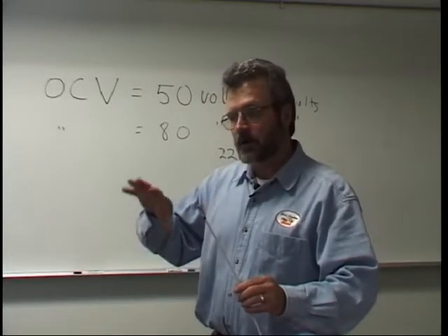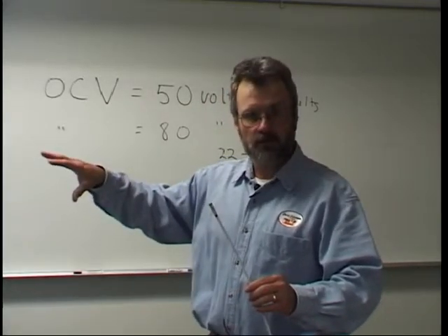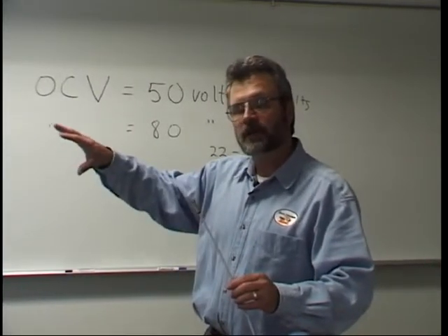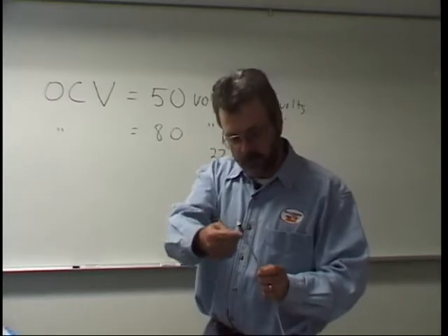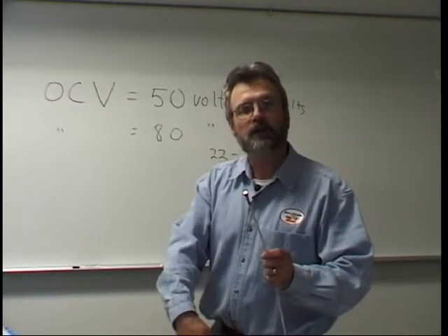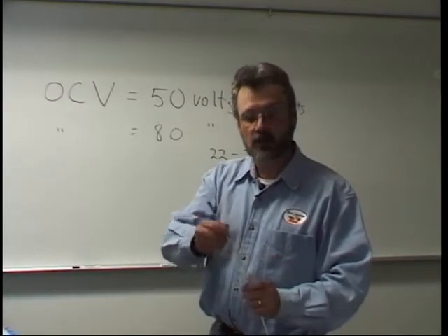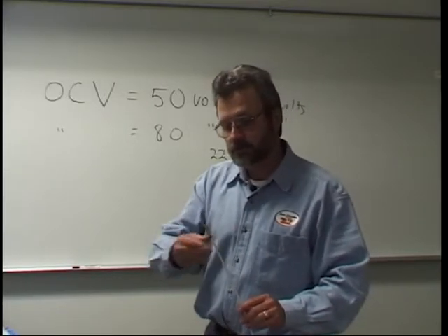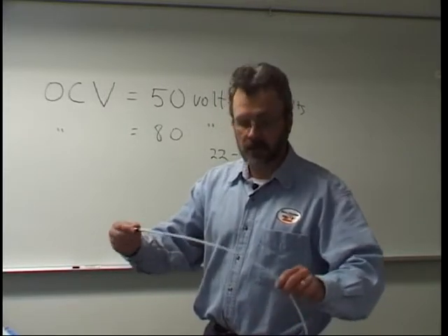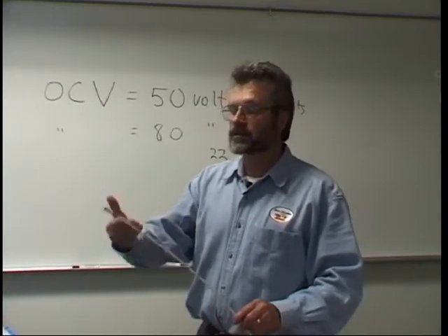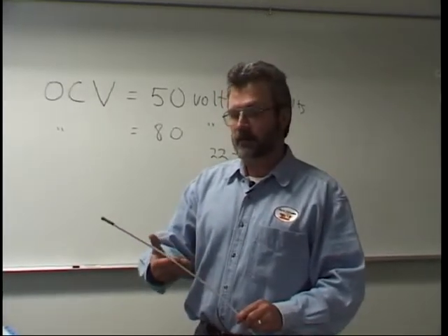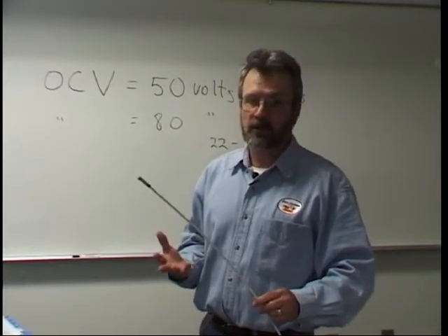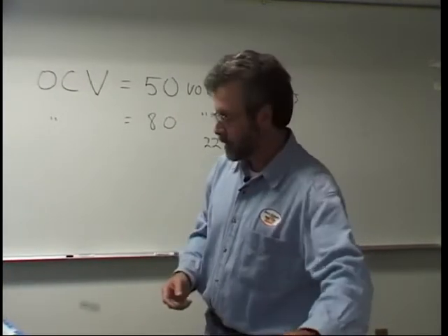I talked about how we put covers over top of those rolls, over the spools of wire. That's to keep dirt from getting on there, because that dirt will get dragged in here, and after a while it will dirty up the insides of these, and they have to be cleaned. You can use a cleaning solution and blow them out with air and reuse them. That's typically done to get as much life out of these. So these are some of the consumables that we talked about earlier. Besides the wire, these things get worn out and they have to be replaced, and they're kind of pricey.